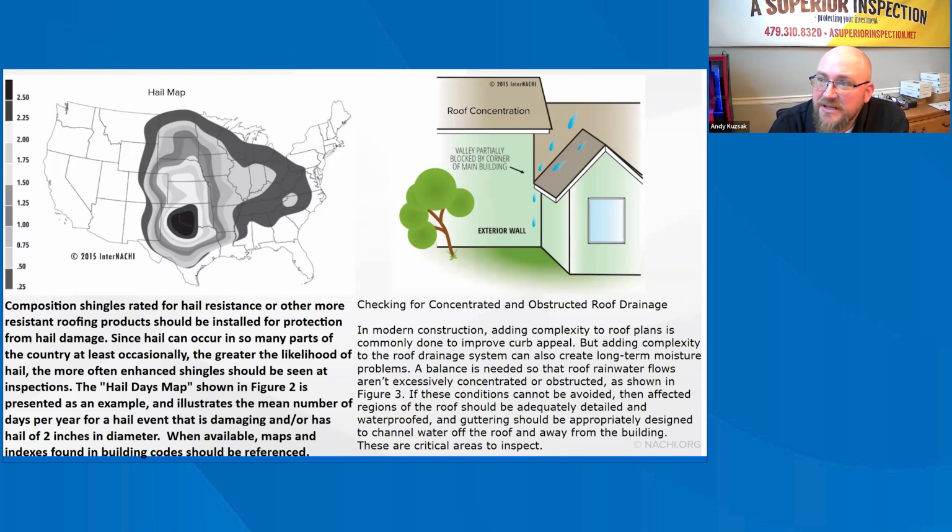To enhance protection against water intrusion and damage to the building and contents in severe wind-driven rain climates, a roofing contractor should apply a continuous strip of bituminous adhesive tape to sheathing joints prior to installing the underlayment. This practice provides a level of protection against water intrusion, even in the event of severe wind damage to the primary roofing. For further backup protection, a self-adhering bituminous membrane may be applied to the entire roof.